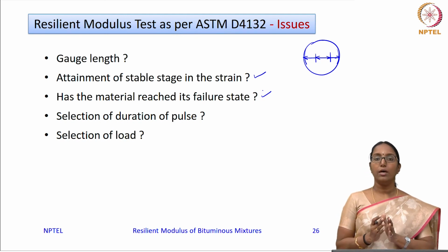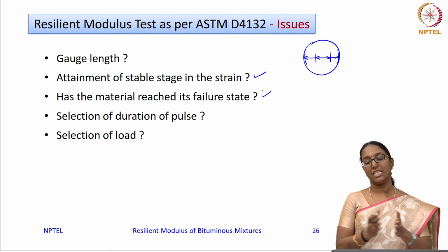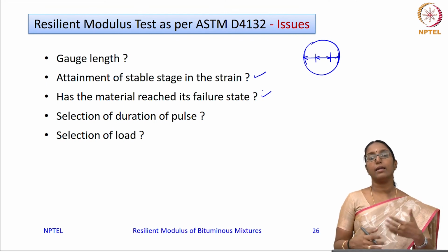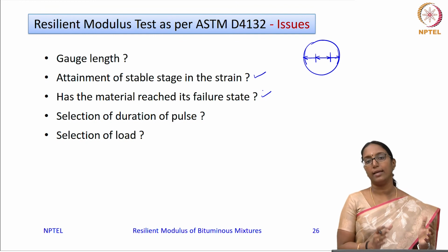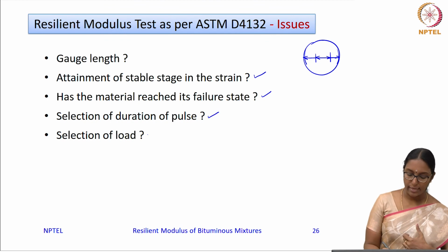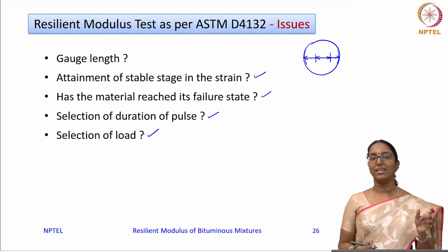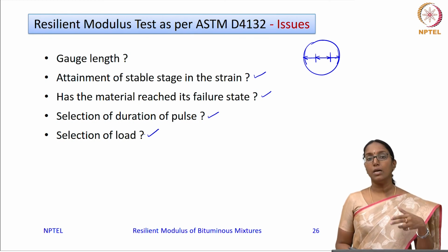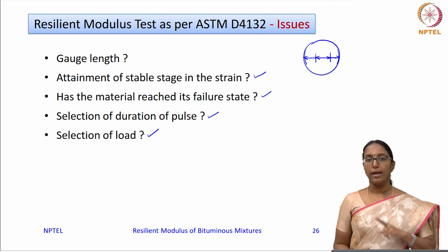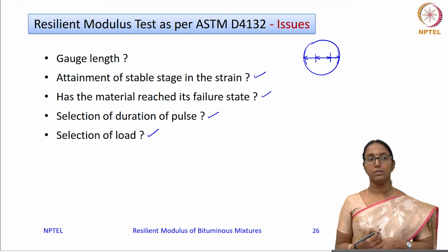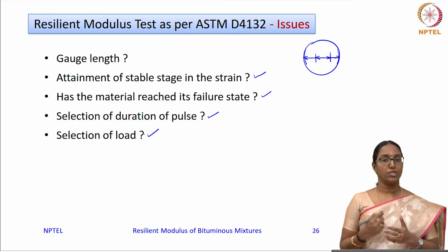So, it is essential to note whether this test sequence that is given will be creating a deformation in the resilient elastic state, because that is what we are looking at. Okay. And next is the selection of load and the load pulse. As is mentioned, this 10 to 50%, will it be sufficient to create sufficient deformation, or will it create more deformation than is required, is one thing. And another thing is the duration of the load pulse. As it is mentioned, you can go from 0.1 to 0.4 seconds. So, what exactly one should take is not clear.